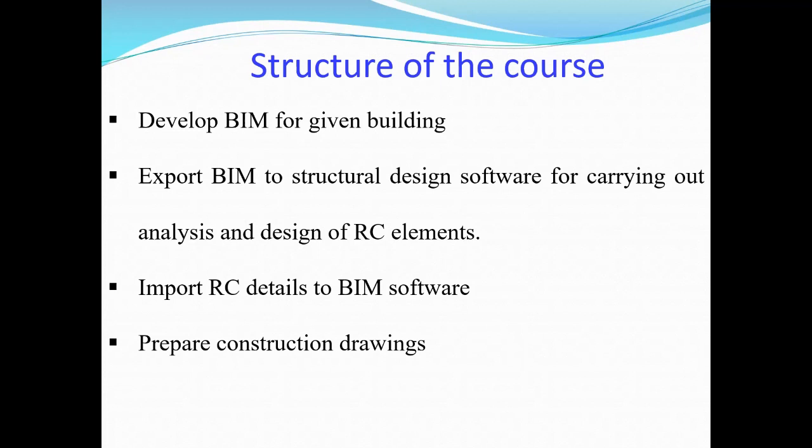After we finish the BIM model in Revit, we export to the structural design software, Tekla Structural Designer, and do the RC element design: beam design, column design, slab design. Here is the important thing about why we want to learn BIM. Later you will know. If you do everything properly in the BIM model, you can export to the structural design software and you don't need to do any adjustment or modification. If you do modify, it's very minor, such as applying the load. You don't need to modify the structural framing or the geometry.